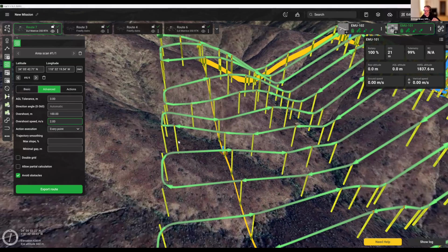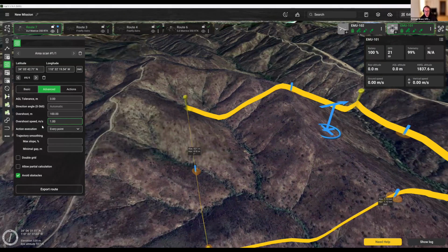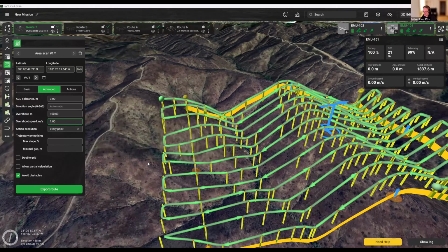Now, this will already decrease the sway in the magnetic sensor that the drone is using, right? So the drone should slow down gradually. From 5 meters per second, it goes here and then it will slow down even more. This is what allows it to corner better, so corner with less shaking. So that's one of the things which you can do. Also, of course, the overshoot speeds you can set to what you want, so 2 meters per second, 1 meter. You can play around with this.